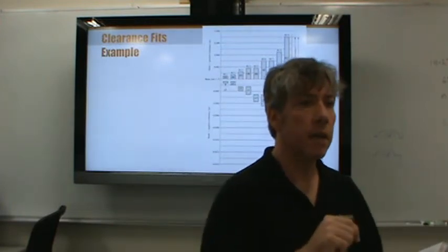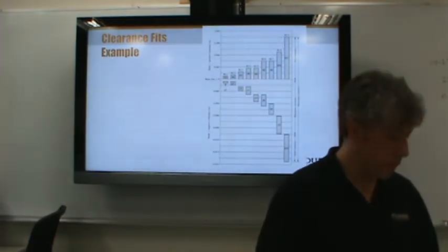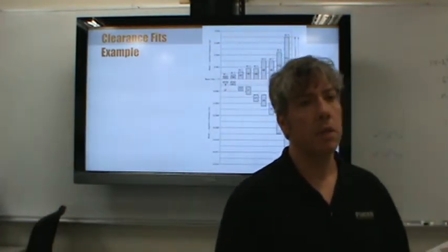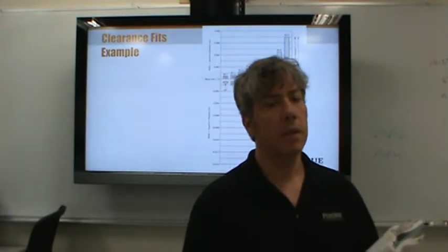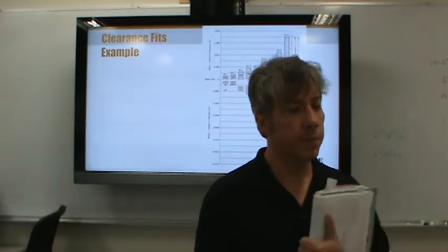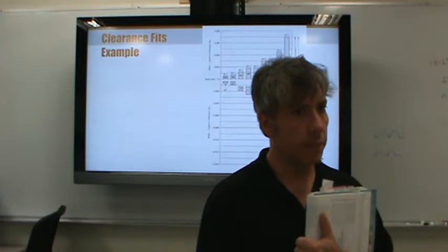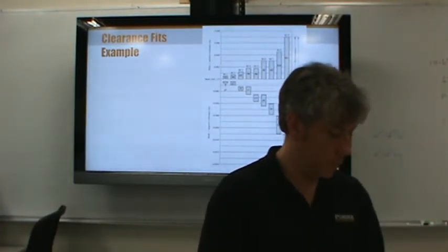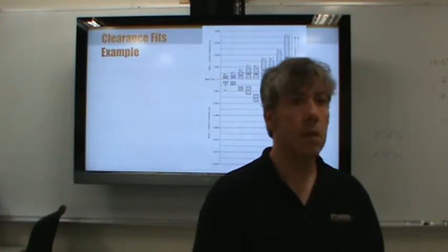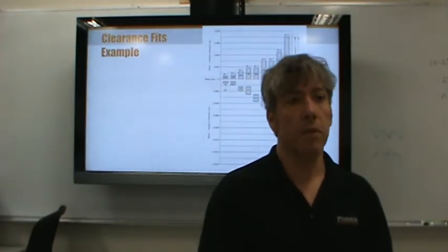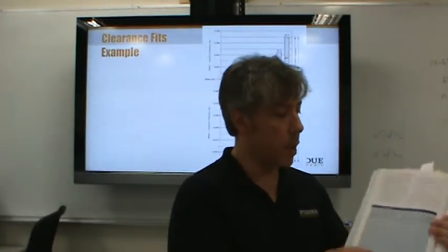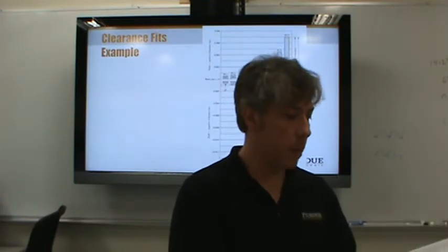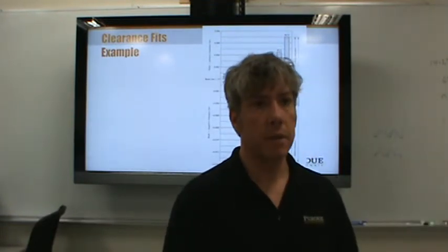Yeah? So on your limits for your hole and your shaft, I don't know, this might be a tough question. Go ahead. It says for a 2-inch shaft, your shaft is -0.4 to -0.9. That's tenths of a thousandth? Tenth of a thousandth. Yeah. In other words, in this chart you're reading off thousandths of an inch. Right. How do you know that it's thousandths of an inch? Says it in the bottom. Yeah, it probably says it, but I just know. Oh, okay, I see it now.